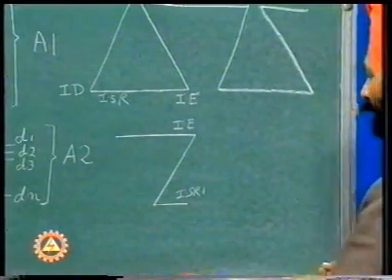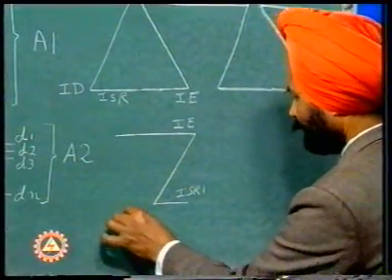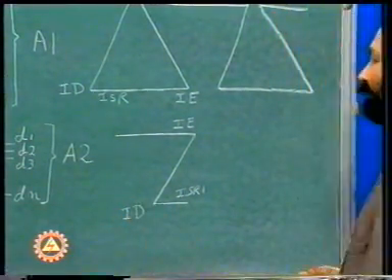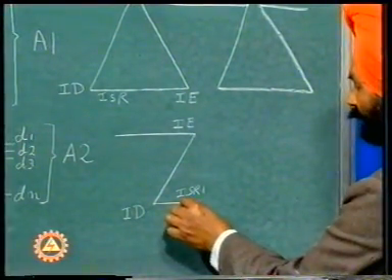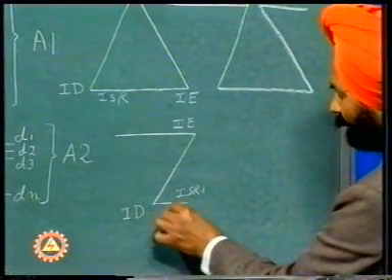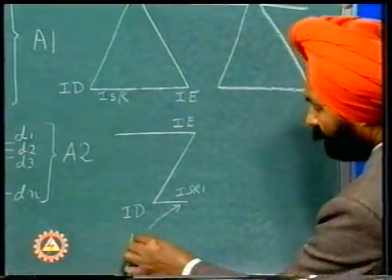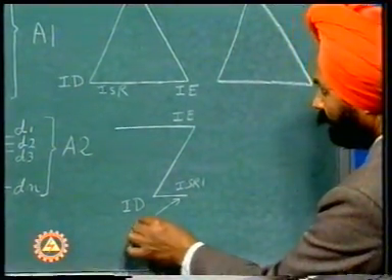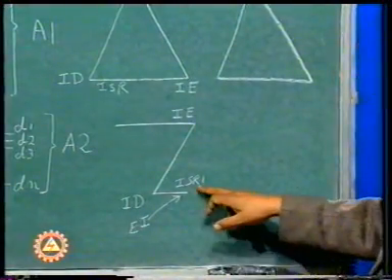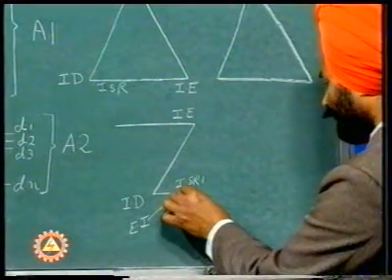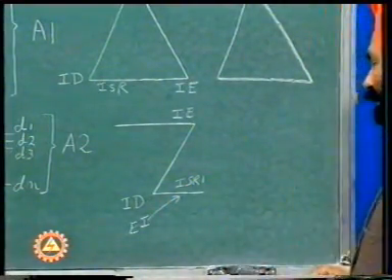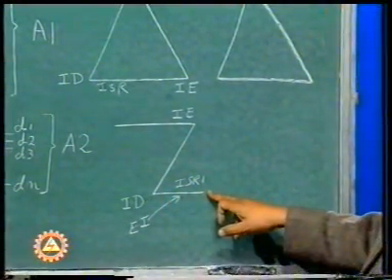The interrupt system of the microprocessor is automatically disabled. Now, if by the execution of some instruction like enable interrupts, we enable the interrupt system of the microprocessor during the execution of ISR1, then the microprocessor is capable of entertaining other interrupts.